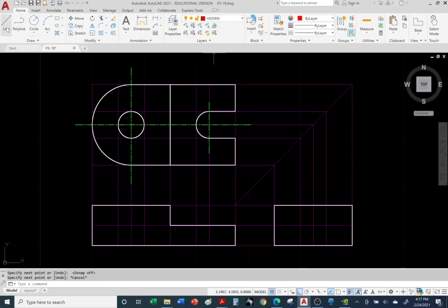Okay, so go to the hidden layer, use the line command. And I know it's supposed to line up with this quadrant. Let me turn on object snap again. And see, that's where I want to go off of, that left quadrant. So I can just track down, yep, and this is where it starts. So I can also use the magenta construction lines. That's where they are there. I created these magenta lines as guidelines, also to guide you along for these first few assignments.